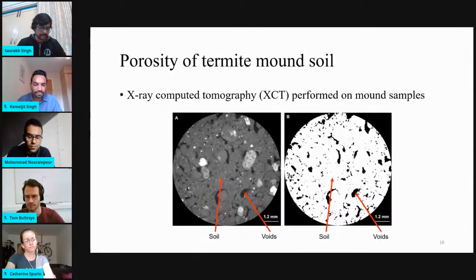Yeah, so we could not tell from this. Our CT scan had a resolution of 13 micron. So pores smaller than that size would not be identified here. We had access to mercury intrusion porosimetry, but it just stopped functioning, and we could not get that analysis done. Otherwise, we could have got pores down to nanometer sizes. So in that sense, this analysis is restricted to only macro pores. It's not detailed. I hope that was your question. Otherwise, you could repeat it. No, that's fine. Thanks.